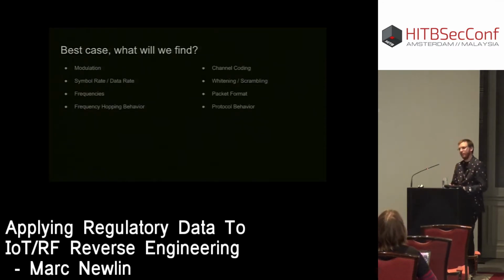So if everything goes perfectly, we really can learn all the information we need to know about how this device operates. That might be all the physical layer properties, and also might be the packet formats and protocol behavior depending on the device. But at the bare minimum, we're hoping to find at least what frequencies it operates on, what modulation it uses, and what channel widths it uses, so we can turn those radio waves into bytes.